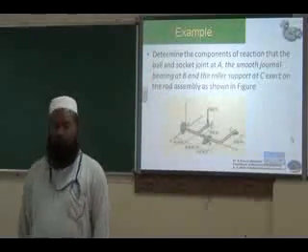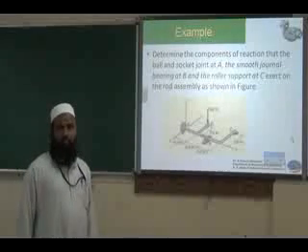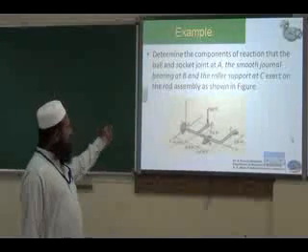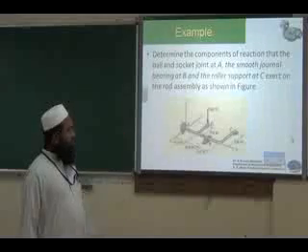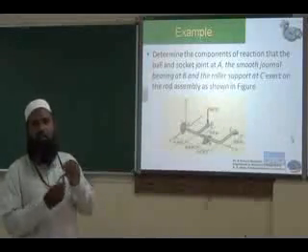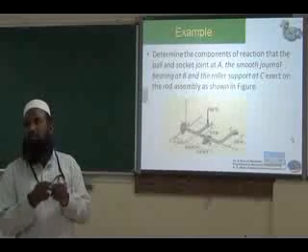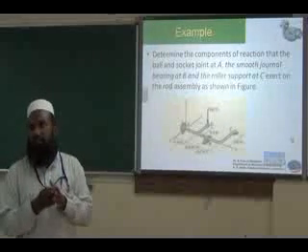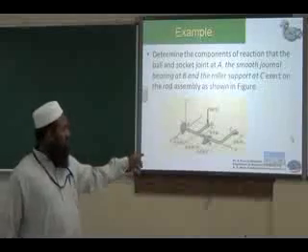Okay. So in this problem we have a bent pipe. This bent pipe has a ball and socket support at point A. So ball and socket means it will allow rotation in all directions, but it cannot allow translation in any direction. So three reactive forces you will have.